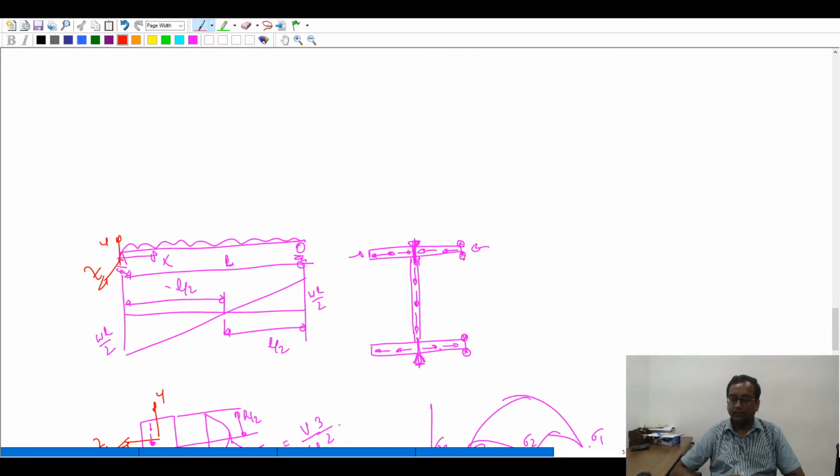No, RCC beams are designed in rectangular sections. The most effective beam section is the I section, wherein you want to spread the material away from the neutral axis as much as possible to resist the load appropriately, right? So, if you look at steel bridges, they will be made of I sections, and circular sections are also used when there is torsion or some other bending effects coming in there.